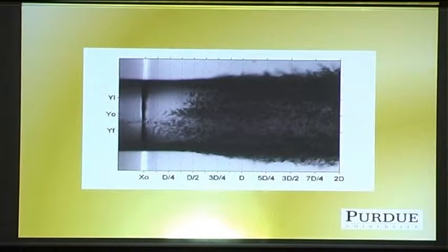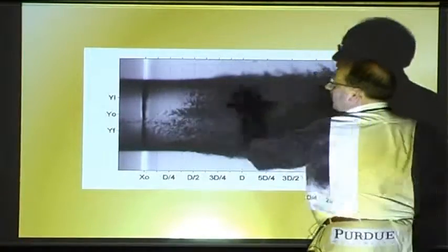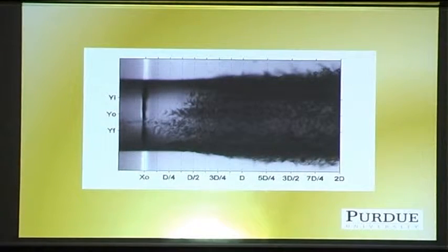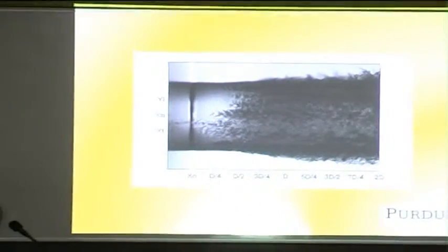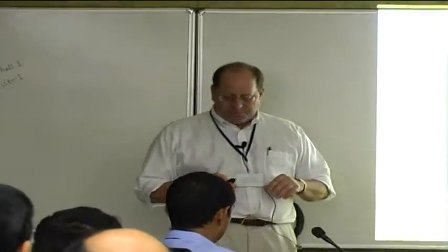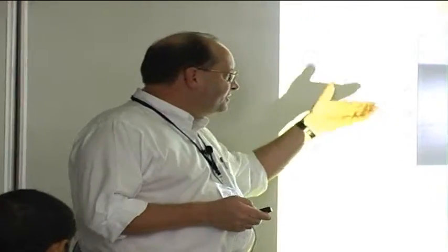How can we make this happen faster? How can we make this happen better? How can we control spray properties through working not out here, but over here inside the nozzle? That's the type of fun work I've been exploring. So we don't dare touch Enrique's 3 beautiful nozzles that he designed and built, and those we've left alone, but we're making a 4th one right now that matches the middle of his 3, into which we can now insert various activation devices upstream of the straight section of the nozzle here and start to create fluidic or mechanical excitations of the flow.